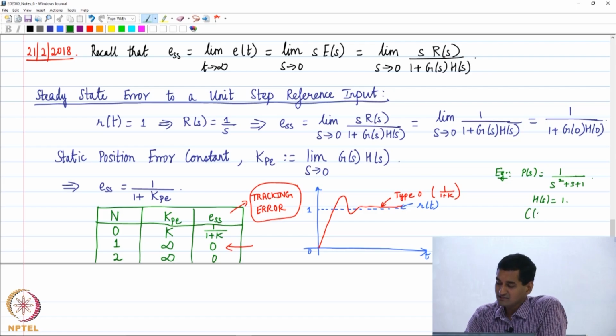I need to use an integrator in the controller block. That is what we discussed. I told you that integral control can guarantee you 0 steady state error if you want to follow step inputs. Now you can observe why. That's why we need to take it with a pinch of salt. We need to look at these things very carefully.